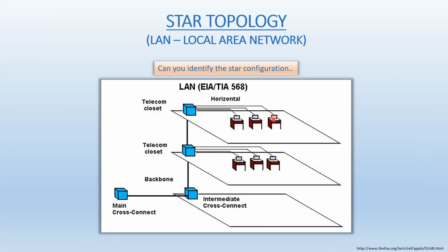The wire will go up vertically to the ceiling, across the ceiling, and then go down vertically inside the wall in a pipe or conduit or any type of raceway. But we consider that a horizontal run. In fact, if that one there would run across the floor and be connected to this closet, this PC would be considered part of this horizontal run.